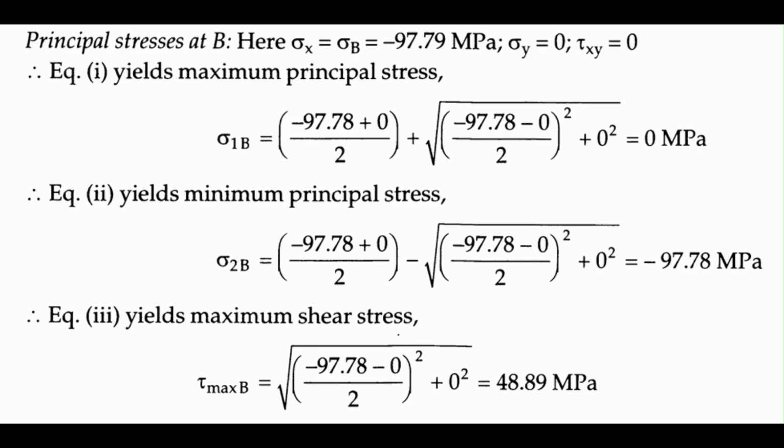So the need to find the stress separately at A and B is because, unlike axial stress, bending stress will have an effect on the structure of the body, because it will bend. So there will be a region of tension as well as compression. Okay, that will not happen in axial load, because that stress is uniform everywhere. But for bending load, it is not just like axial stress. So you have to find the principal stress separately at points A and B. So we have solved the second part too, that is the bending load or bending stress case.